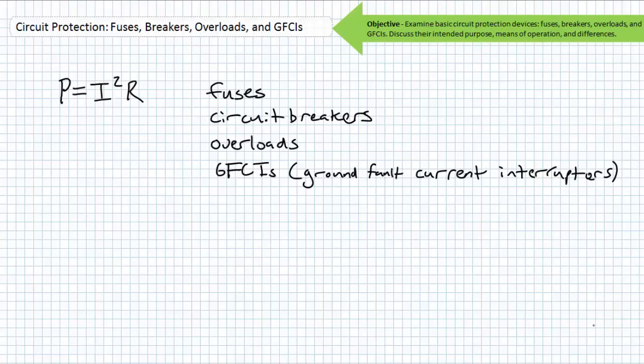Circuit protection devices are always placed in series with the electrical load they are intended to protect, because elements in series with one another carry the same current. This is the most basic of series properties, and protection devices make use of this fact to selectively enable or disable current flow. If a circuit protection device is closed, it allows current flow to the load, whereas an open protection device does not.